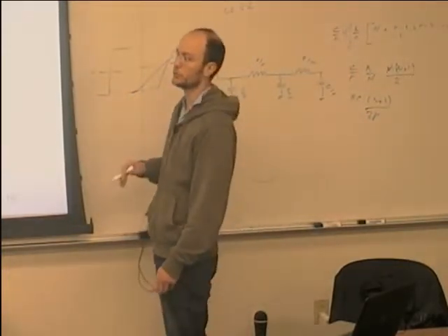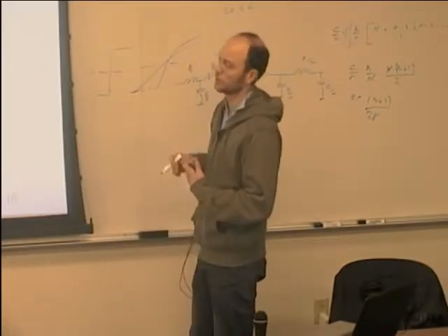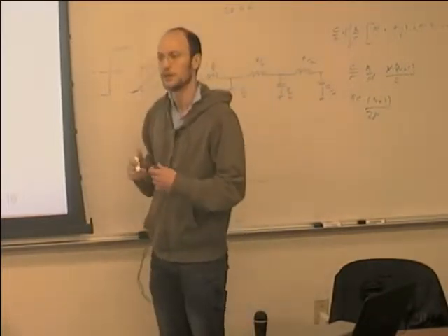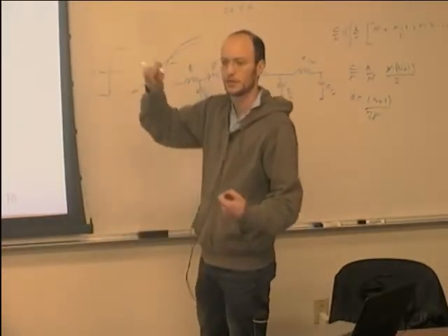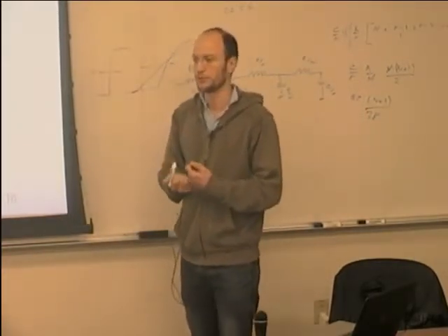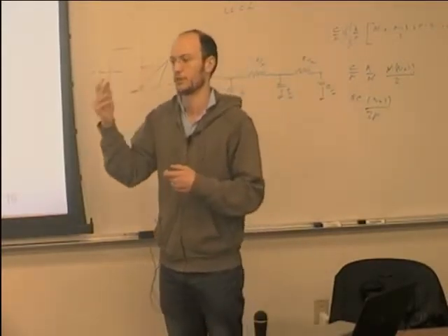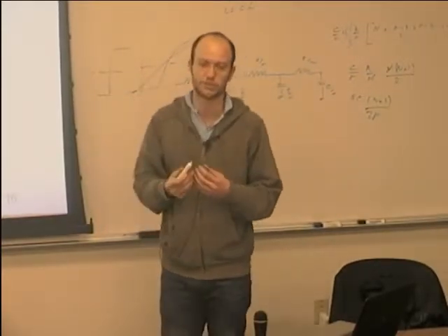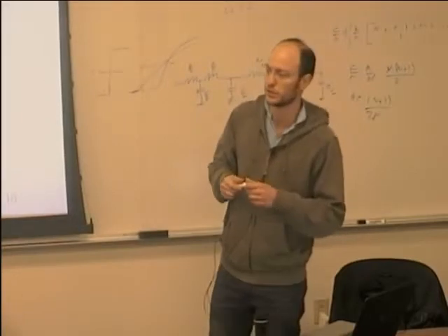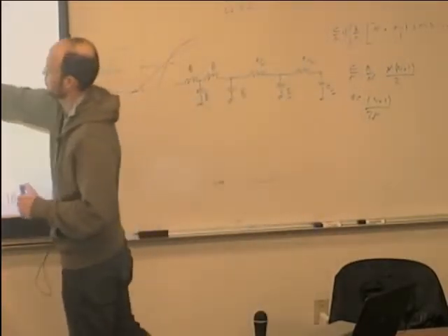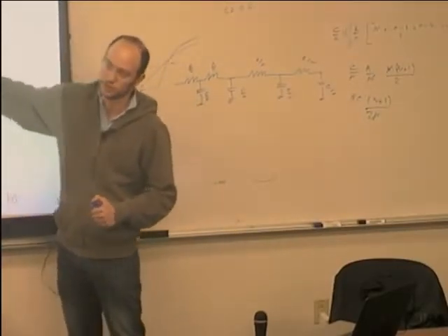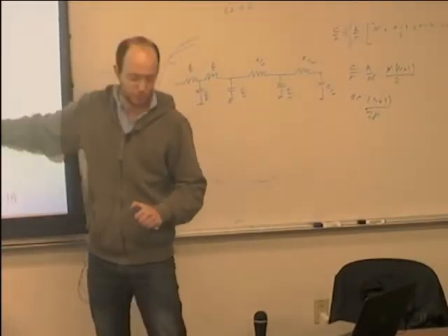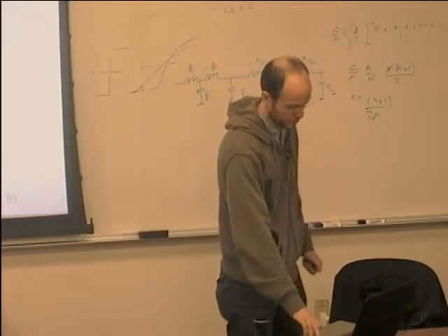And for example, this could be important. I don't know if you guys talked about short circuit power, but if you have a slow rising waveform, then you have more short circuit power than if you have a fast rising waveform, okay? And so for some things, this actually is important. But I would think that most often you wouldn't need to use anything bigger than this. Most often, actually, you will just use this. But this is probably okay for most cases.